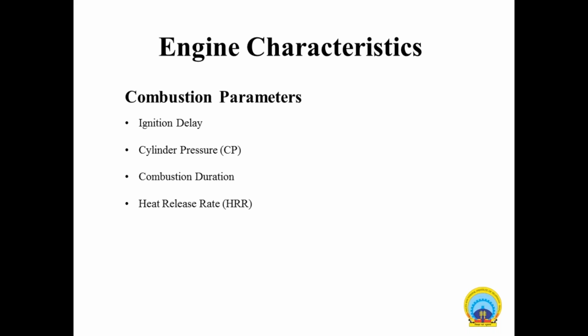This delay period consists of a physical delay, where atomization, vaporization and mixing of air and fuel occur. Other than this, chemical delay is also there. It is attributed to the pre-combustion reactions.